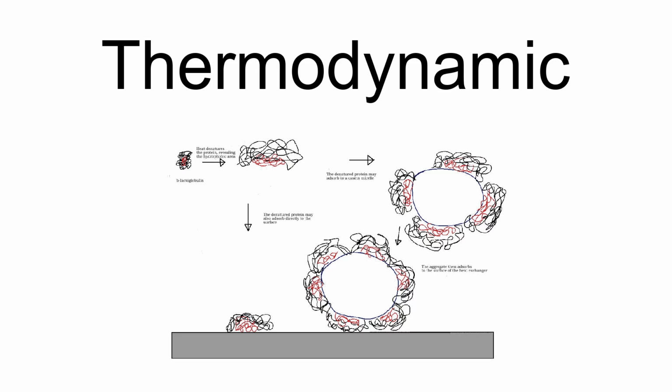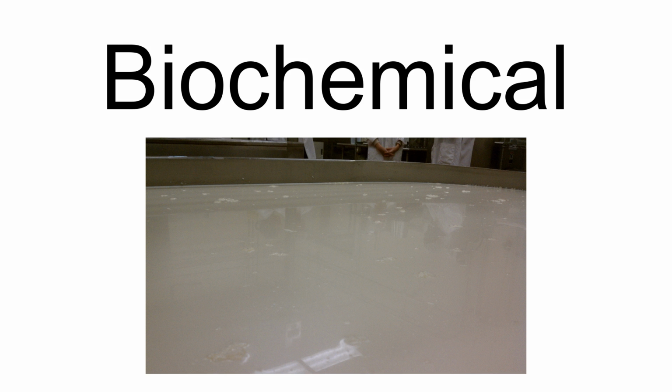While the aggregates can explain much of the protein fouling found in milk processing, this does not account for it all. A third type of fouling has been discovered that is explained by the chemical interactions of the denatured beta-Lg proteins. Beta-Lg contains 5 cysteine residues, 4 of which are covalently bonded to each other, forming an S-S bond. When beta-Lg is denatured, the 5th cysteine residue is exposed to the water. This residue then bonds to other beta-Lg proteins, including those already adsorbed to the surface. This produces a strong interaction between the denatured proteins and the surface of the container.